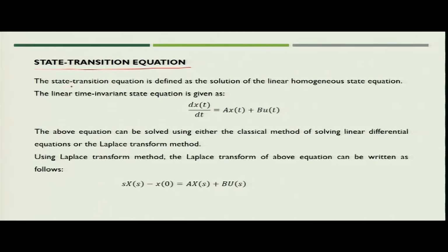The state transition equation is defined as the solution of the linear state equation. The equation which we have, linear time invariant, that is dx by dt equal to Ax plus Bu, is the state equation. Now, the above equation can be solved using either the classical method of solving linear differential equations, or we can utilize the Laplace transform.